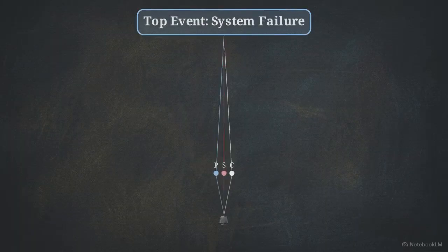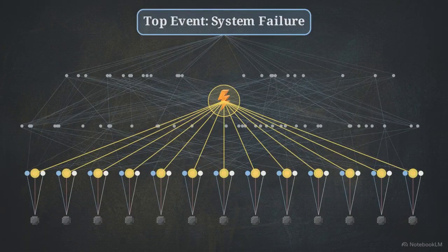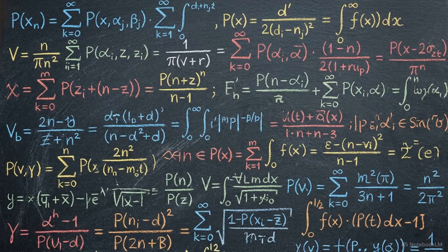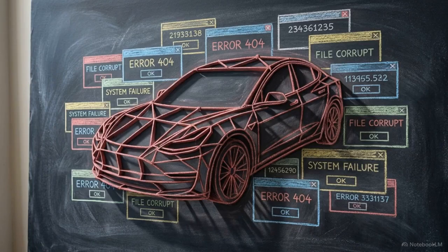A common industry practice is to map all 3 of these fault types into a single, massive fault tree. Engineers assign a probability to the physical wear, the command logic, and the environmental stress, wiring them all into the same probability equation. Treating environmental stress exactly like physical wear and software logic inside a rigid equation is a statistical error. It generates false data that actively compromises the safety validation of the entire vehicle.